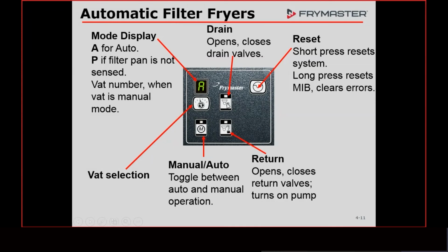The problem may be that something got stuck in one of the valves and it can't close all the way, so it's not in the fully closed position. If it's not in the fully closed or fully open position, it's going to flash. It could be something simple. We clear the valve out and then close it all the way. Once it's in the all the way closed position, it should work just fine. That happens. Clogged valves are not that uncommon.